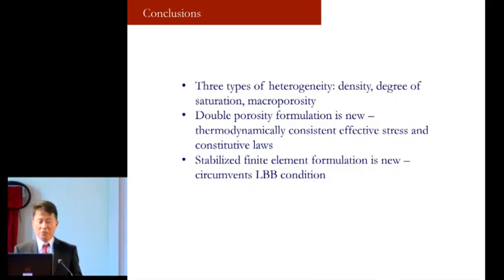So let me just conclude with the following. There are three types of heterogeneity considered in this work: density, degree of saturation, and macroporosity. The double porosity formulation is new. It's based on a thermodynamically consistent effective stress. The stabilized finite element formulation is also new and circumvents the instability associated with volume constraints.